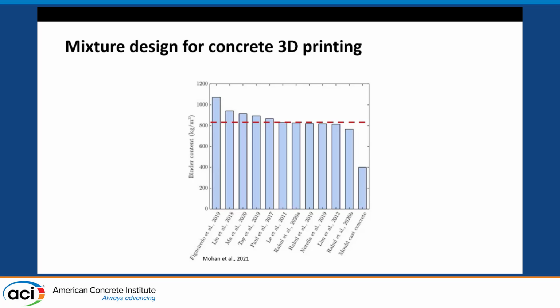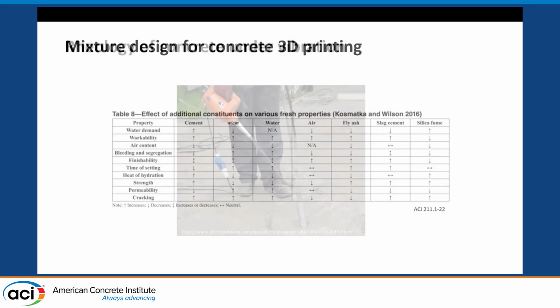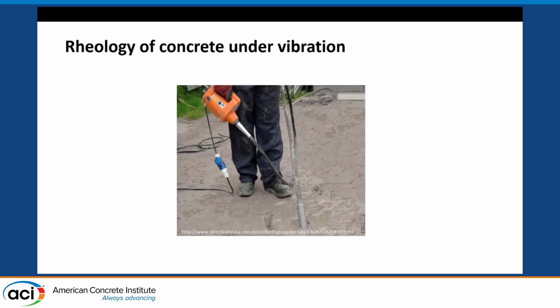So actually having coarse aggregates will benefit us in all of these issues. But that would also mean we are printing traditional typical concrete for which we know the behavior already, right? Say workability, the title of this session, I guess. Predicting workability is pretty well known when it is conventional concrete. So can we do something similar? Print concrete, which we have been using for a long time. We have experience with this material. So that is where my work is focused on, actually incorporating coarse aggregate into concrete.